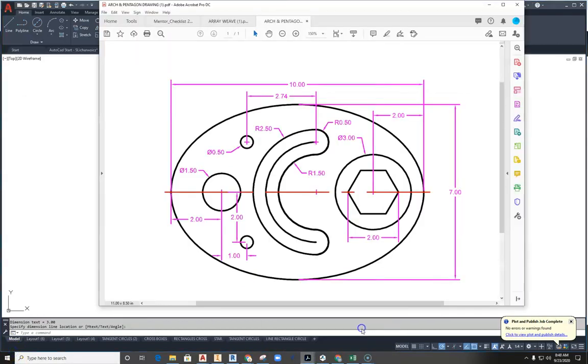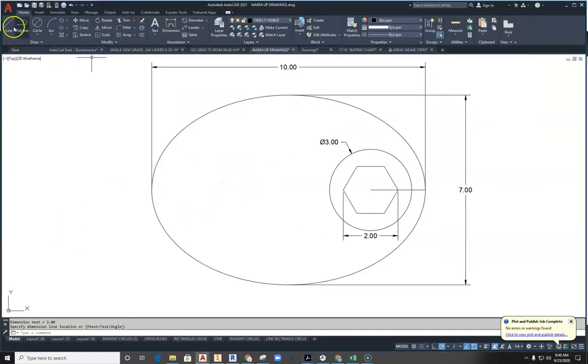All right, so jump back into the drawing. Now, as we look at this, we've got to kind of see, well, what goes where next? Well, I can start working on this, but the dimensions, I don't get a dimension from this side. Most of it looks like the dimensioning is coming from this side. So here's a 2.74 for the top of this circle, which then I can find center. I think I've got to start building from this side over now. So let's go from here and get a 2-inch line coming in this way, and then get this 1.5 diameter circle next. So we'll grab my line tool, find this point here. Well, I'm not getting that intersection point, so let's go to the center, mouse straight over, click, and come over to.